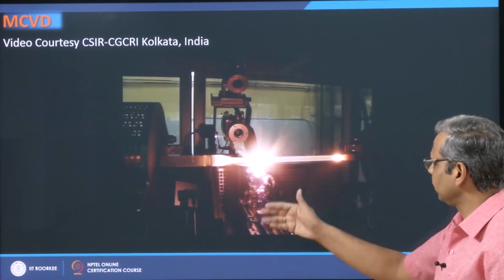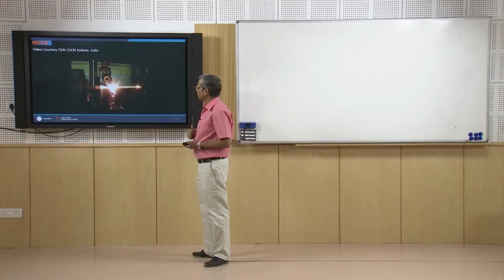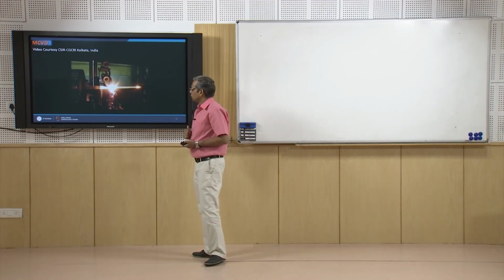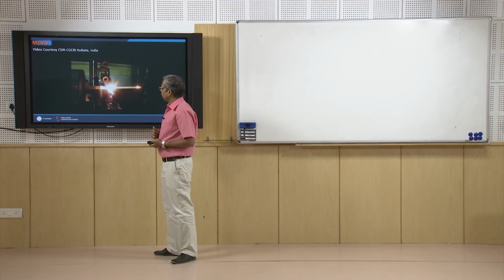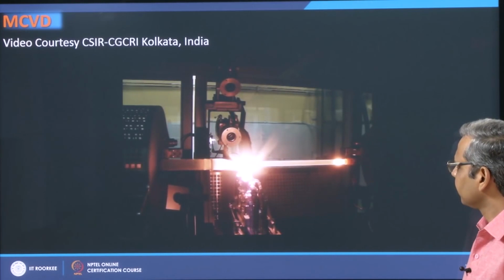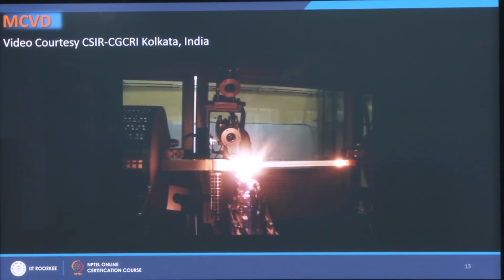When it falls under gravity, it pulls the fiber down, and this fiber now goes through various stages. Here the diameter is monitored using a diffraction technique, using a laser. Then you coat this fiber with an acrylic coating. Here you monitor the concentricity of the coating.